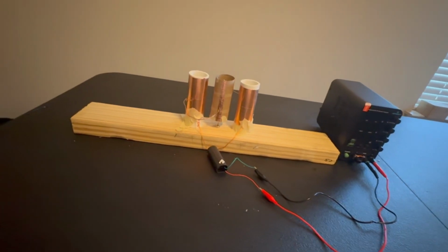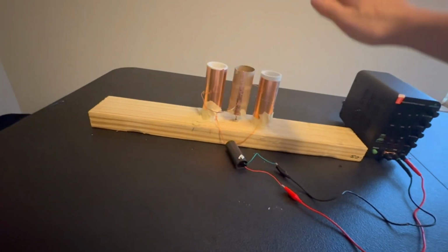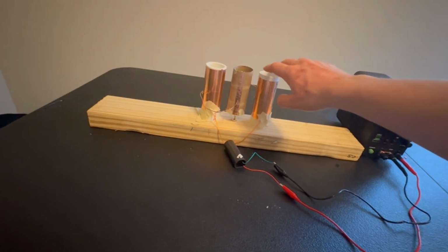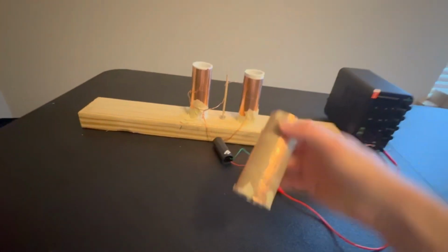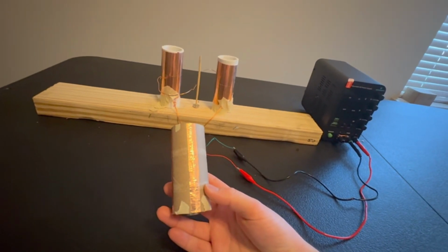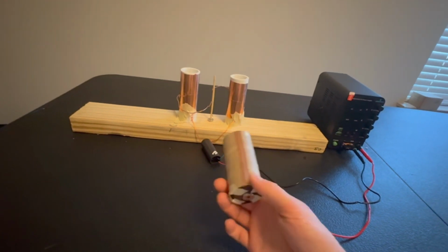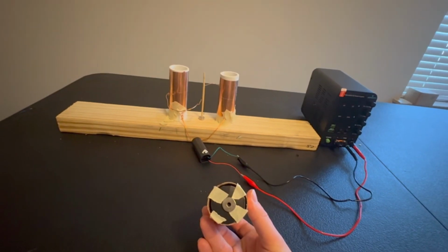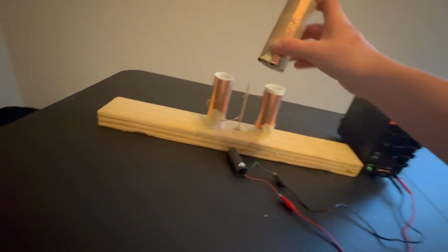Here are the stators. Here's the positively charged electrode or stator, and here's the ground. You can use negative, but in this test we will be using just ground. In the middle is the rotor. It has 4 blades or conducting surfaces. And due to electrostatic motors having such low torque, in lieu of bearings, we decided to go with a magnet here to help minimize friction and allow it to spin more easily.